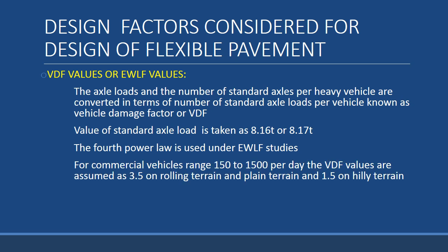Then for commercial vehicle ranges of 150 to 1500 per day, the VDF values are assumed as 3.5 on rolling terrain and plain terrain, and 1.5 on hilly terrain.